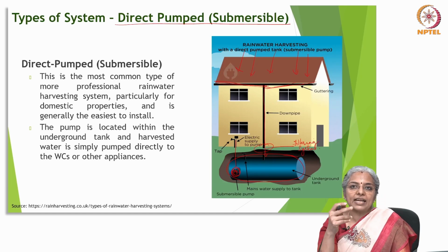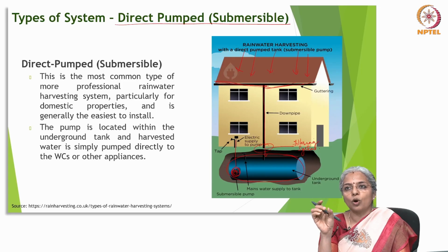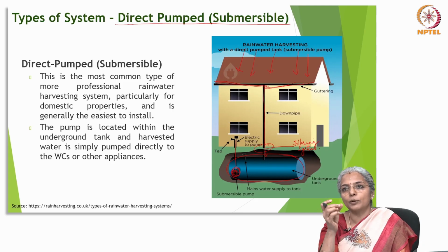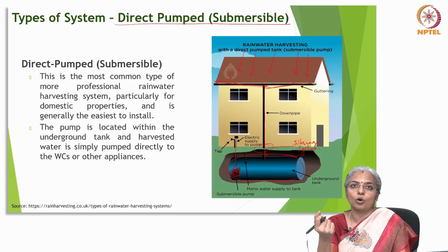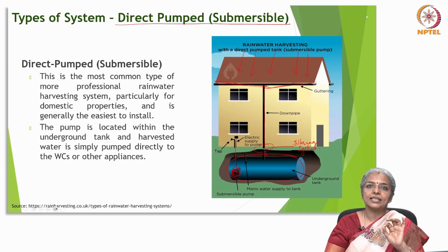So, if this tank gets into the danger of becoming dry, then a small amount of main water is also fed into it to maintain the supply. So, this can be used even for small commercial properties, but they have to be very small, because such a system can tend to be a dual pump arrangement also, but it has to be primarily domestic, otherwise very small commercial properties.